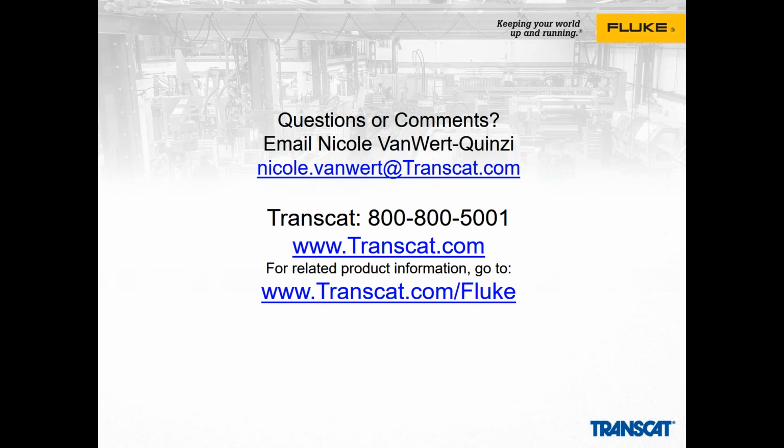You see kind of cheap imports where they haven't really taken the time to spend money on the filtering on the input, and they become very noisy loads. But the electronic loads are so universal now. Everything inside a plant has some kind of electronics. If it's automation equipment, you'll have switch mode power supplies on PLCs. You'll have drives operating with things like gate operated thyristors, or electronic loads, and they all take those gulps of current out of the system, and they cause current distortion, which in turn can cause voltage distortion.